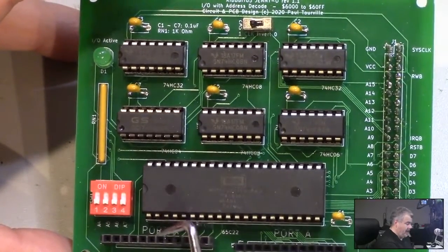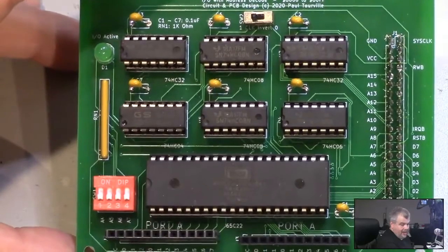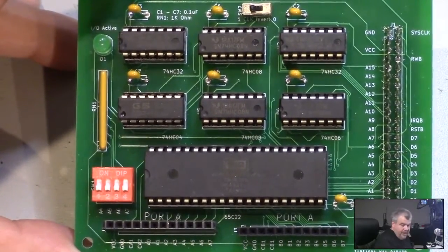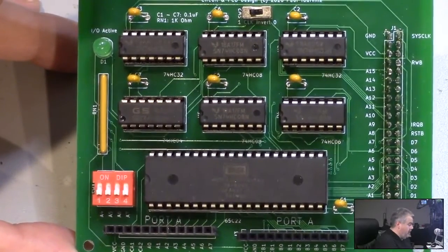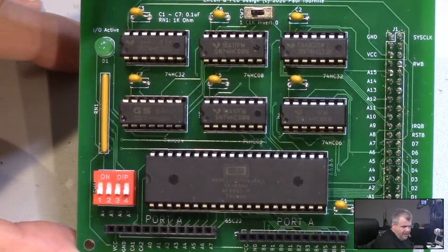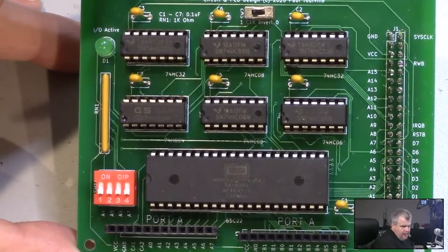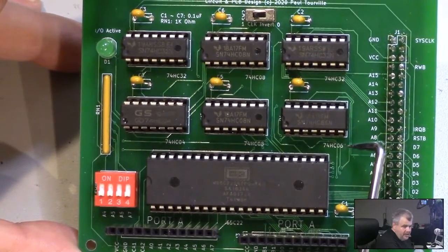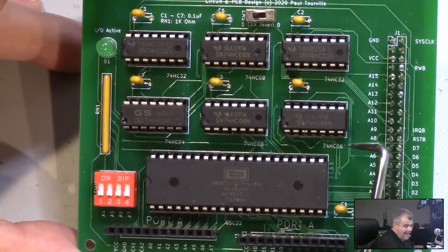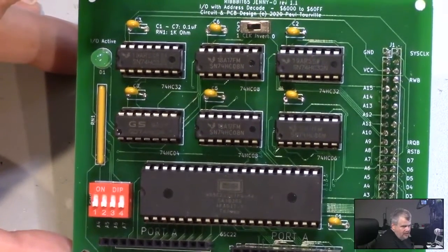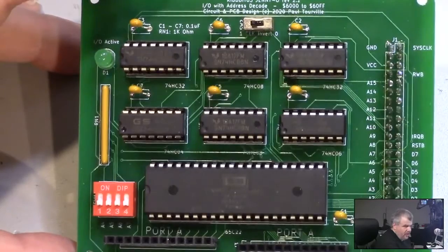Now you may also notice that port A and port A, well, that's wrong. That's a problem with the silk screen. That is my fault in laying out the board. So that has also been fixed on Rev 1.2, which again has not been sent out for manufacturing. And the label on this chip, the 64HC06, that's wrong. That should be 74HC86. So that's the XOR there. So the silk screen issues have been fixed in the new version of the board.